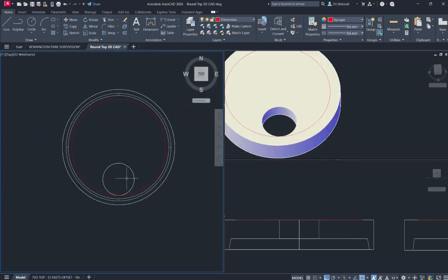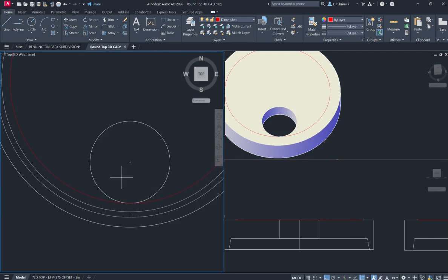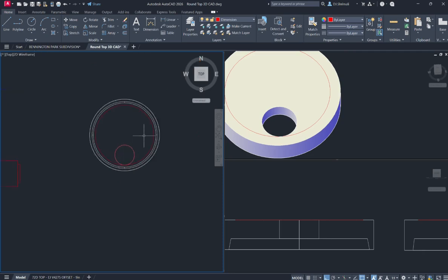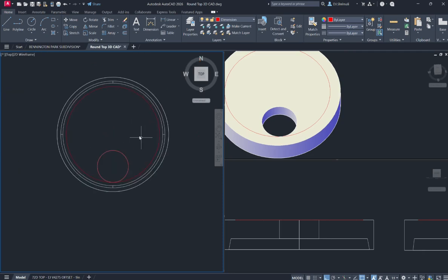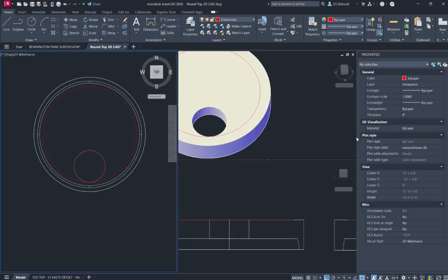And I'm creating the circles to find out the cover. So usually we do a 2-inch cover from all the outside edges, and the reinforcement that we show, that we usually draw, is from a 1-inch cover from the inside face. So not the joint, from the inside face.